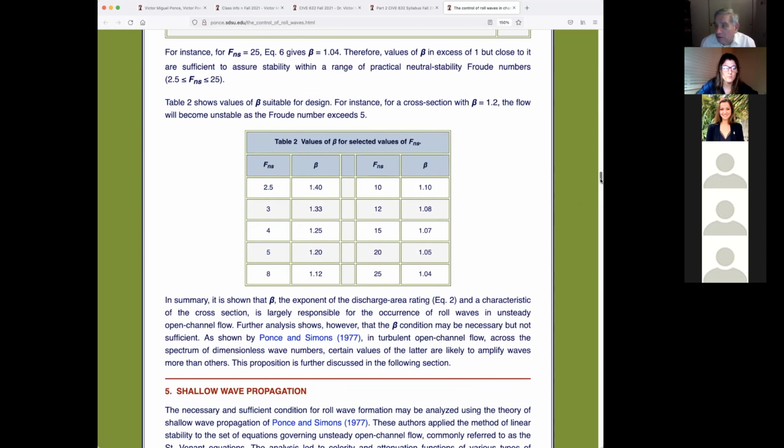It's 5/3, okay? Or 1.5, which is the Chezy. So you don't want to be there because 1.5 is already putting you in the category of 2 in here. And 2 could be achieved. If 1% slope is Froude number equal 1, roughly, then about 2% slope is 1.5. By the time you get to 3% slope, you're already Froude number equal 2.